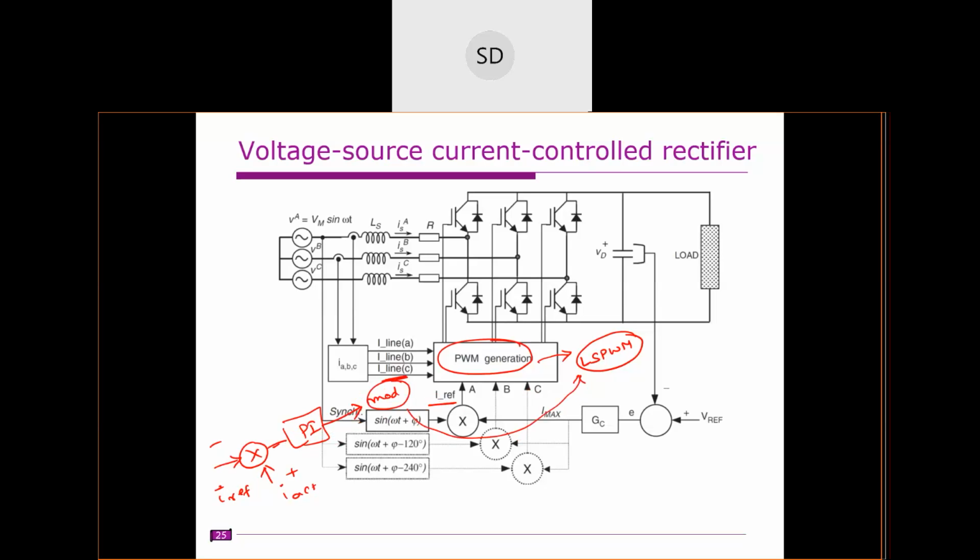Okay. So you have two changes here. When you are using a 3-level inverter, the first change is here. Earlier you had only one capacitor. Now you need to control 2 capacitors, right? The sum will be controlled. The sum will be compared with the entire reference voltage, and the difference we need to compare with 0, right? The rest of this is the same.